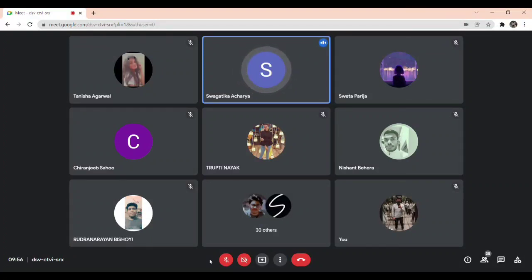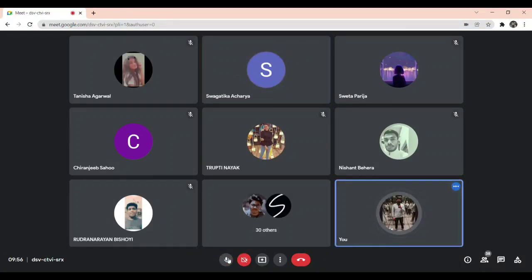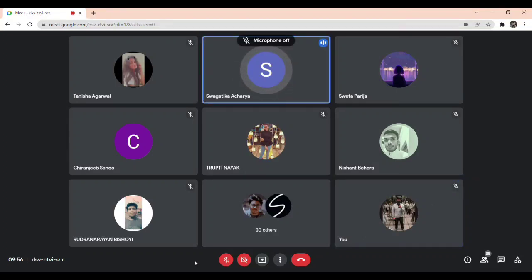From that, you can put your values. Vi equals 16 volt, in place of Vi you can write down your 16 volt. So the equation will be 16 volt minus I into R, which is 1 kilo ohm, minus I into RL, which is 3 kilo ohm, equals 0. From that, you can find out your I value. I will be 16 volt divided by 1 plus 3 kilo ohm. Correct? Correct or not? Because that is Vi minus IR minus IRL equals 0.